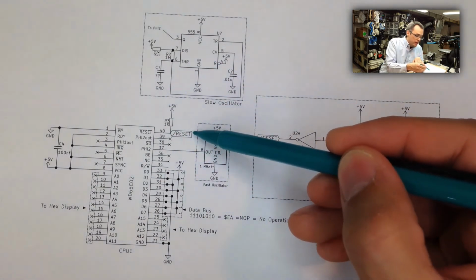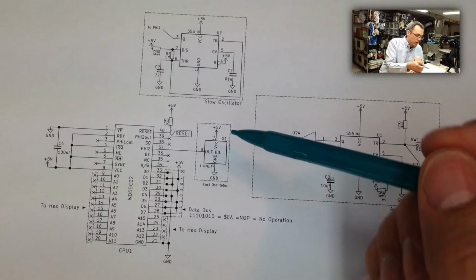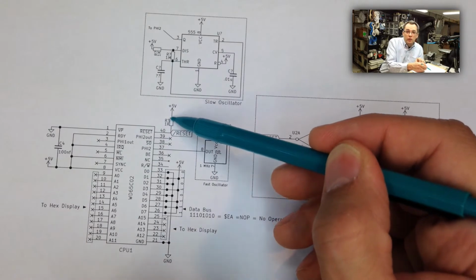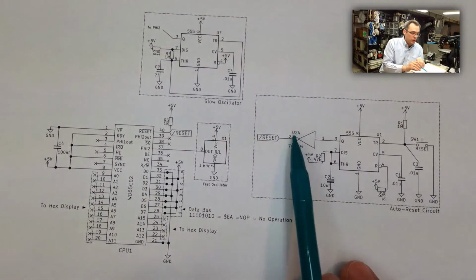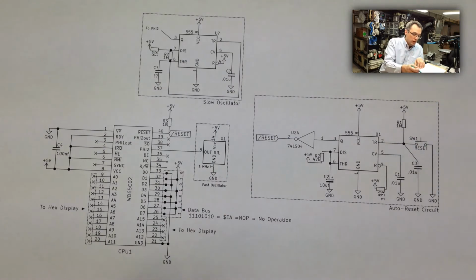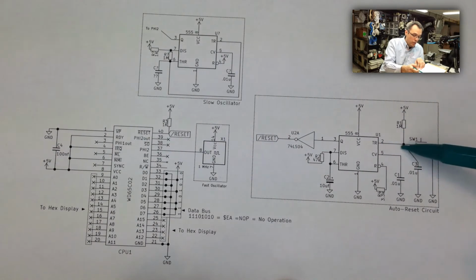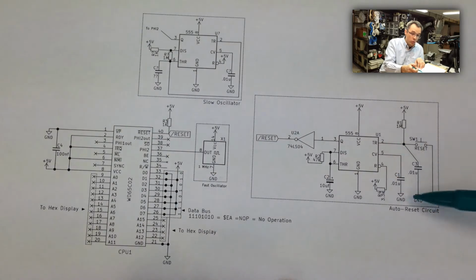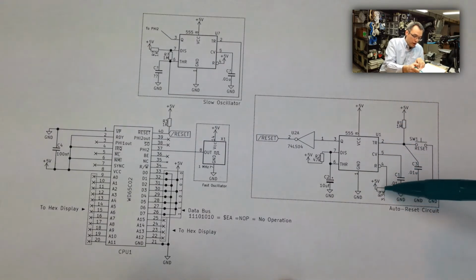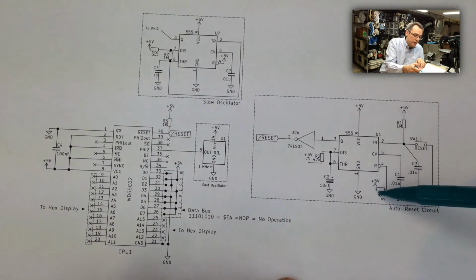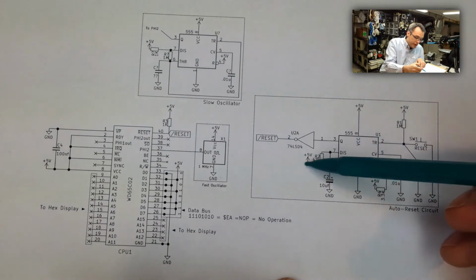And then here we have our reset line, which comes over to our reset circuit here. Our reset line has a 1K pull-up resistor to keep it positive, keep it from floating, and then when it actually resets, it gets a negative pulse. Our simple reset circuit here has 5 volts to pull this high when we're not pulling it to ground to do the reset or when it's not triggering. We've got the reset pin of the 555 pulled high as well, because it needs that reset pin pulled high to say, hey, I'm running. Right here is our timing circuit.